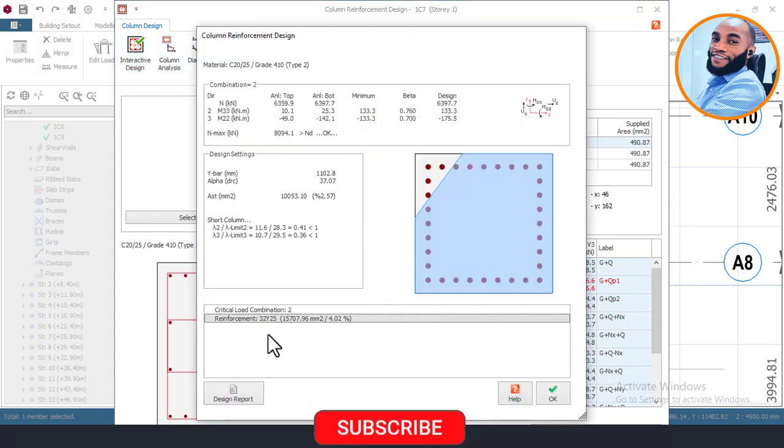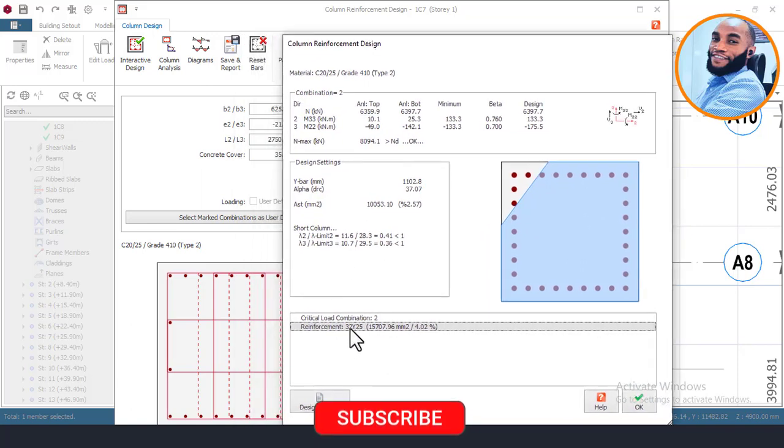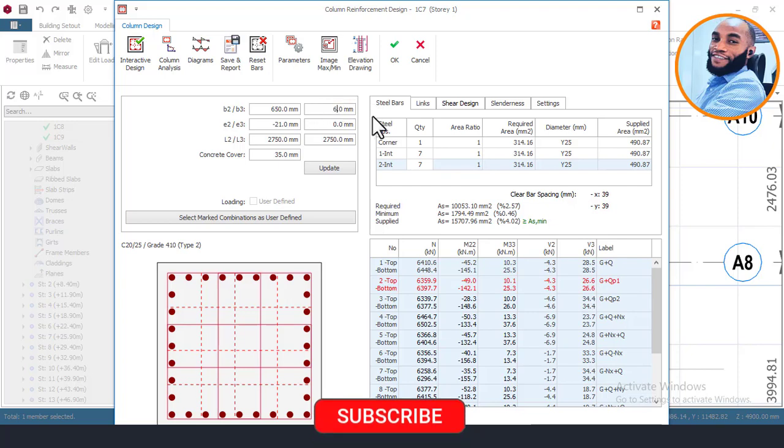Let me see. So you can see that basically 625 is okay to carry the load imposed on that column, but we are having 32 number of Y25. So I think that just to have uniform column sizes, which I've been using 650 before, I'll just maintain 650 and all that, and also to help reduce the number of bars from 32 to at least 24. Or sorry, to 28, I think so.